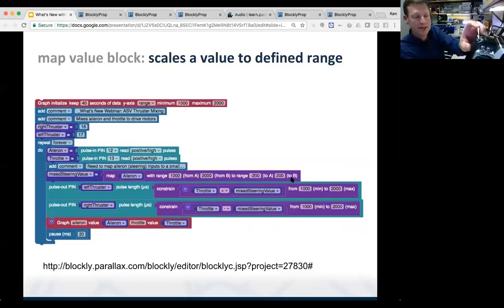Yeah, that's an excellent programming tip. So if you put something out there into the wild, you need to be able to take control over it at any time. So what Carol was doing was not just monitoring the receiver channels, like the aileron, the throttle, but she was also monitoring a gear switch so she could take over control of it again. Excellent point.